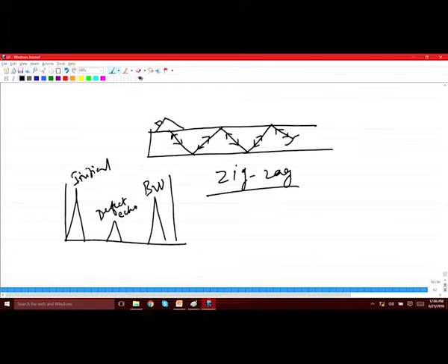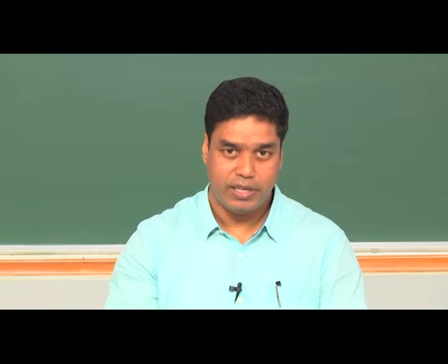Okay. So, that means for weld inspection, where you do it by angle probe, you need to find some other reference which can be used like the back wall signal. Okay. So, let us see in this case what is that reference that we can use to characterize defects and find out the defect echo on the display.